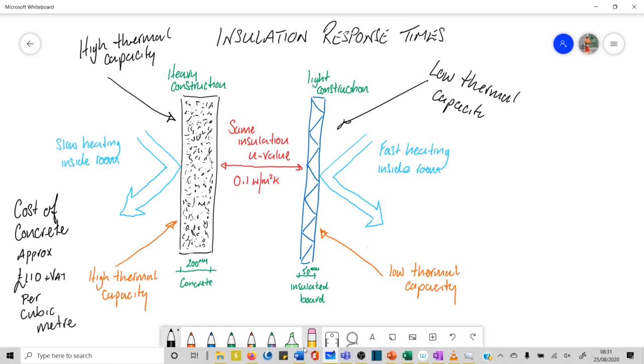So you would simply work out the size of the wall, the length of the wall, and then the depth, the thickness, the width, the height, and so on and so forth, to work out how many cubic meters of concrete. And then of course you can either buy these prefabricated, so that the wall slabs arrive already made up for you, which would be more expensive, or you could pour it in situ, which would need a formwork system to hold the concrete in.